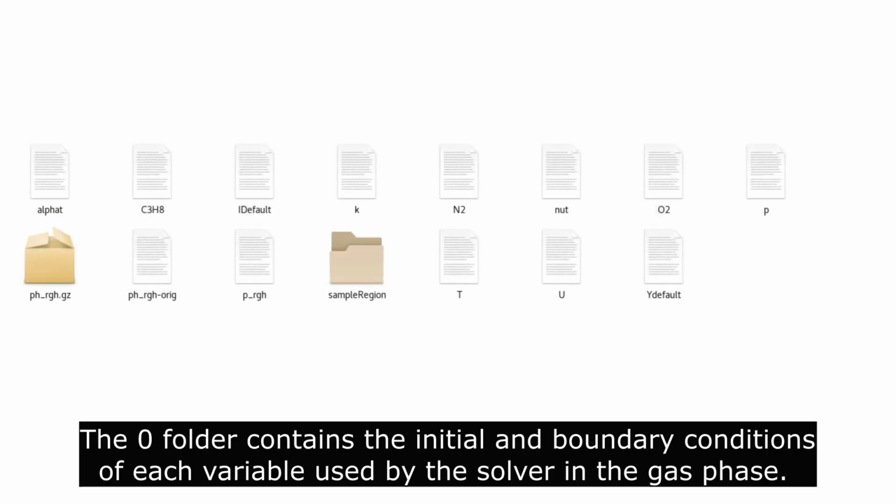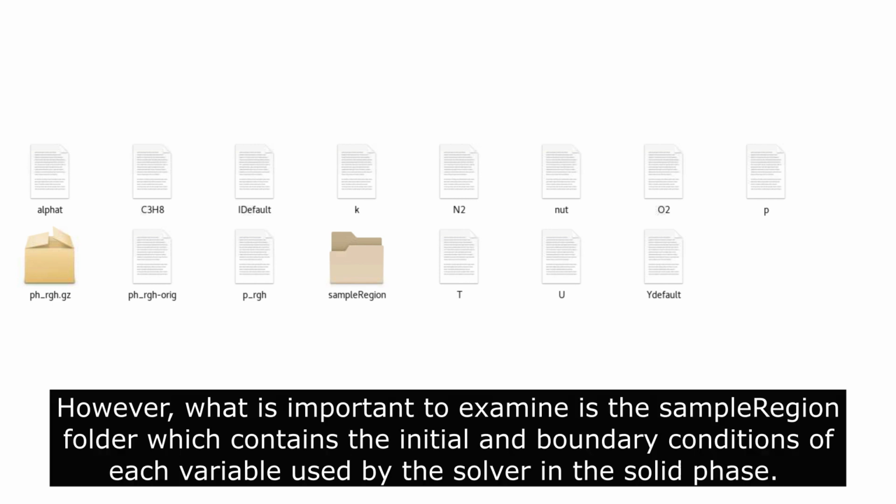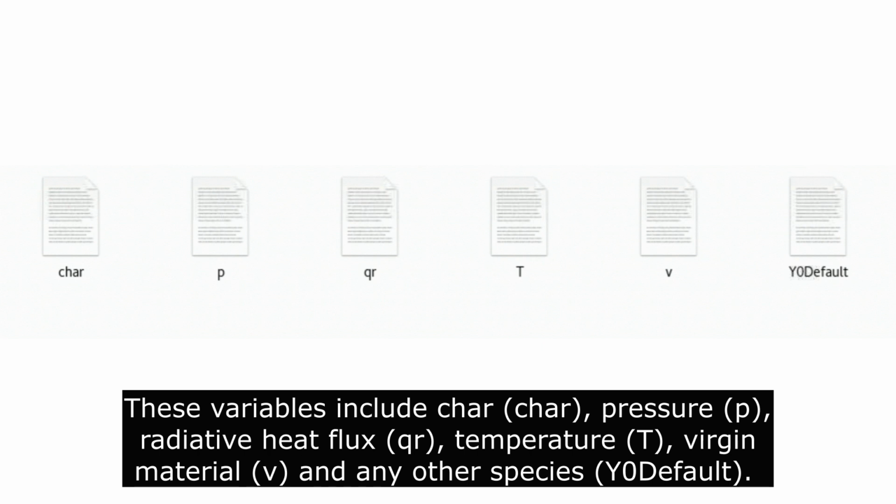The Zero folder contains the initial and boundary conditions of each variable used by the solver in the gas phase. Since the gas phase will not be solved, these files are less important here. However, what is important to examine is the sample region folder, which contains the initial and boundary conditions of each variable used by the solver in the solid phase. These variables include char, pressure, radiative heat flux, temperature, virgin material, and any other species.